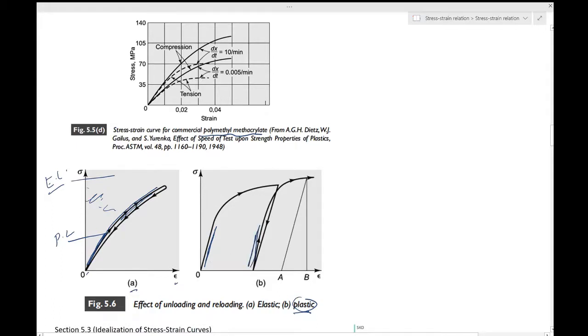So what is happening in this experiment? For a plastic behavior, again, this is a steel or aluminum alloy which you have seen in figure 5.5, you gradually increase the load, and the proportionality and the elastic limit have definitely been lost. Proportionality is lost over here, and once you arrive, you start unloading, and it will fall back to this permanent strain.